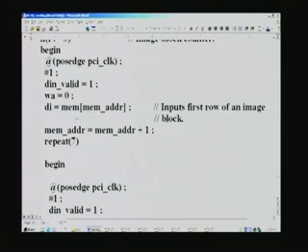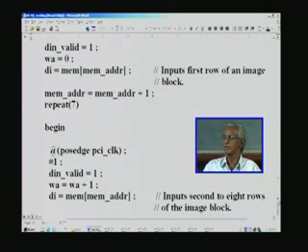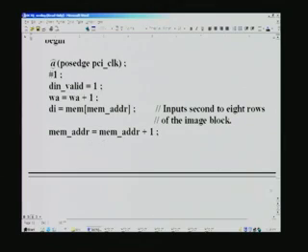From that we start reading right from the first location, the 0 location here, and input it to the dual RAM. This is nothing but the DCTQ design core. Every time we do this we increment the address so that we go to the next location and keep on writing row-wise in a block. You need 7 more times to complete one block, because there are 8 such rows, and that is what we do here by repeat. This is the block which does precisely the same, and they are all exactly the same.